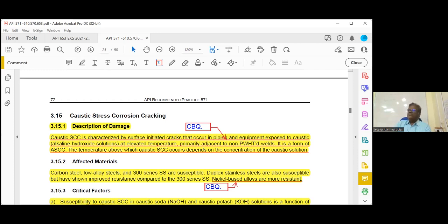Generally, PT should not be used as the only method. But if it is happening inside the surface and you want to check from the outside, we cannot do surface NDT. Then we have to go for shear wave ultrasonic testing. That is angle beam or PAUT. What is PAUT? Phased array, we have to go for it.